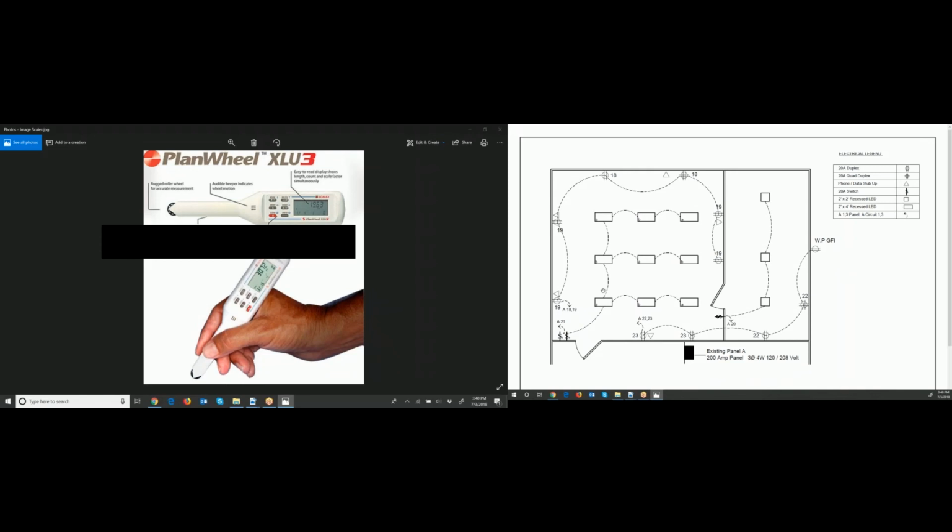To take off from fixture to fixture, I might start down below this light fixture to give a little over roll for the amount of MC cable that goes, again, up and down out of the fixtures. So I'll roll from this fixture and past that one, again allowing for over rolling, allowing for the riser, the part that goes up, okay? So I just over roll to account for the amount that goes up. I do this with feeders, with MC cable, any conduits.